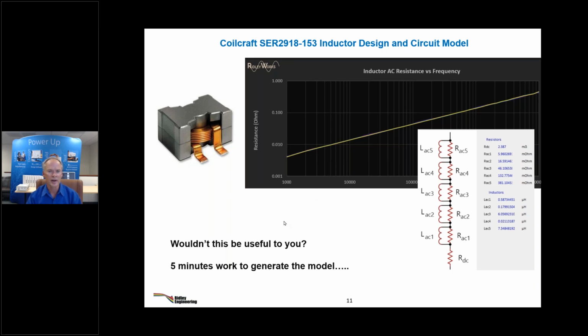In the current slide, RAC is increasing, but LAC is random. Yeah, that seems weird, doesn't it? You do see strange effects sometimes. Sometimes you see a linear drop of the LAC, but then sometimes you'll see that the L can almost stay constant, and then sometimes it actually drops. And then in some of the curve fitting models, we saw that the leakage inductance sometimes becomes negative. So we didn't let that happen. We force it to zero.